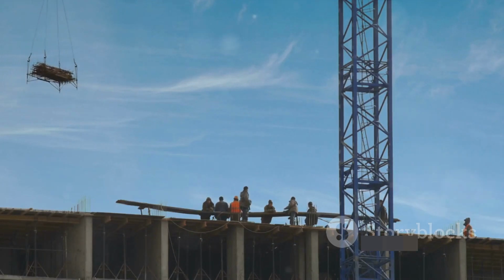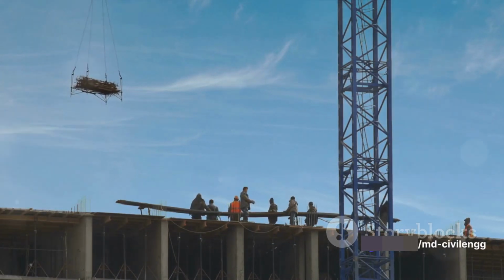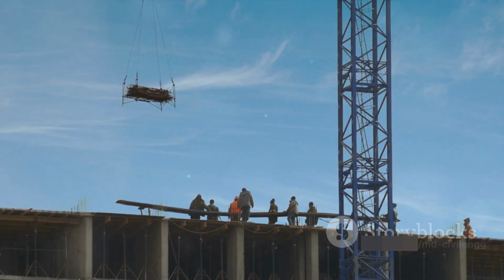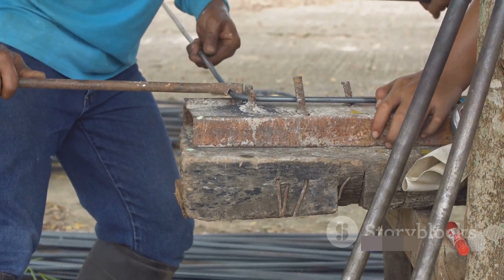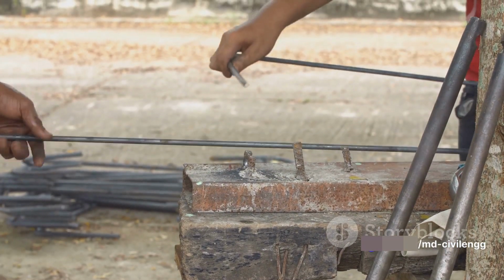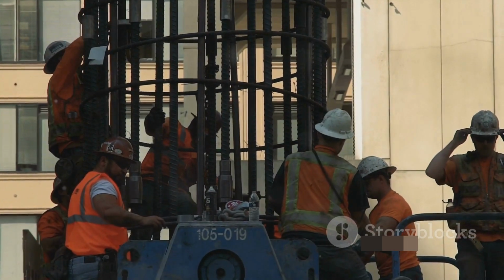And what about the maximum area of steel? Well, if the bars are not lapped, it's 6% of the gross area. But if they are lapped, the maximum area reduces to 4% of the gross area. The minimum number of bars needed for reinforcement also varies. In a rectangular column, you'd need at least 4 bars. For a circular column, the minimum number of longitudinal bars required goes up to 6.